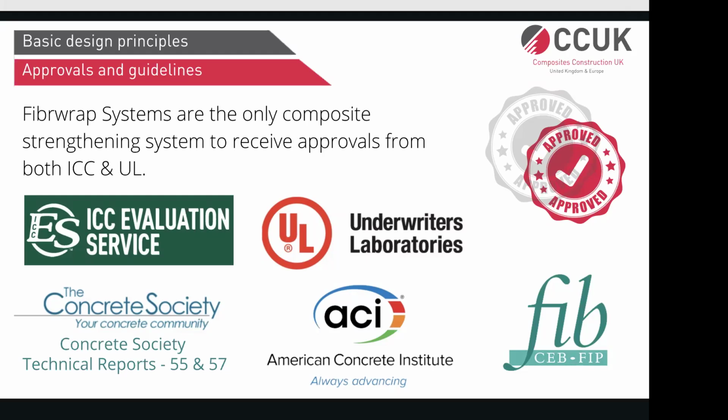In addition to that, there is an international approval which pretty much all the major carbon fiber suppliers have. That is ICC approval, the International Code Council, the governing body for design codes around the world. They provide this ESR listing, so some of the systems have this. UL approval is basically for fire protection systems of FRP. So if somebody comes to you with a fire protection system over the FRP, you need to check for this UL rating, what sort of UL rating that system has got, because that's the authority which provides the approval for that.